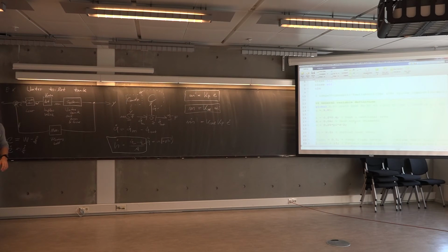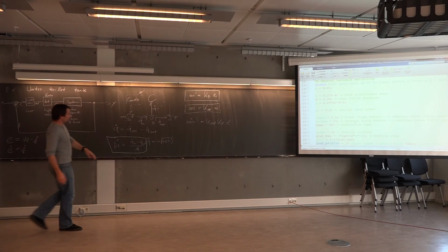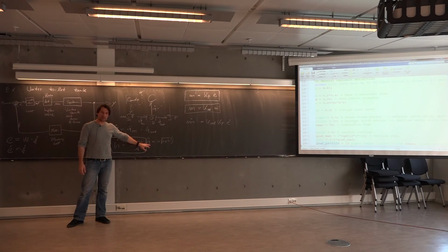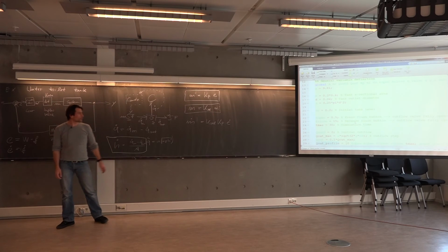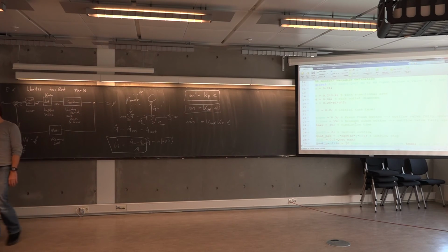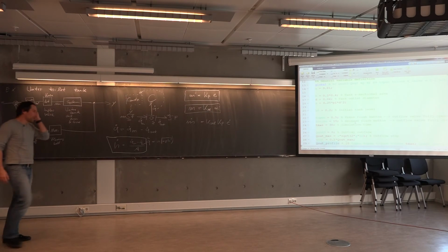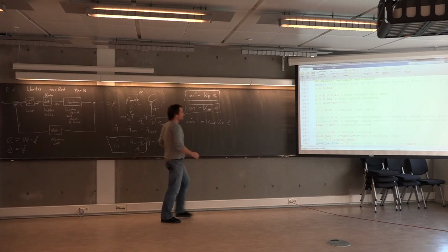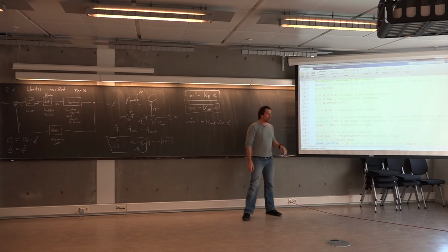Then we have some Matlab script where we assign parameters using global variables. We use this concept here to get a physically reasonable value for the outflow. We use dimensions as you would encounter that in an ordinary toilet, and we assign a certain profile for this outflow.